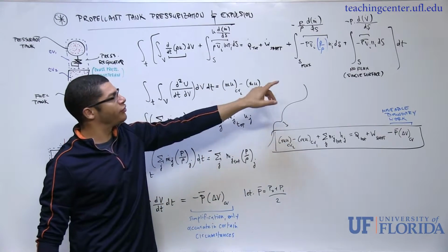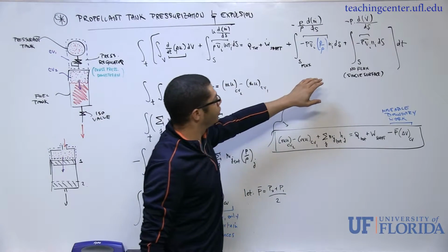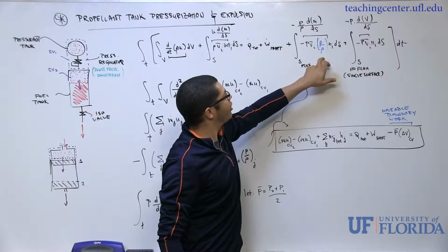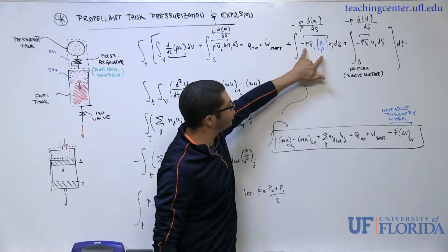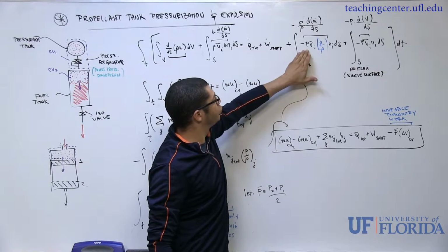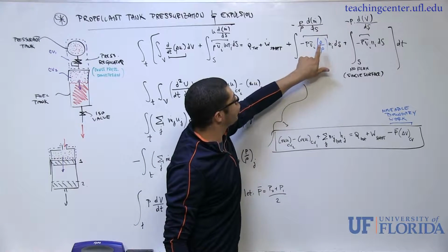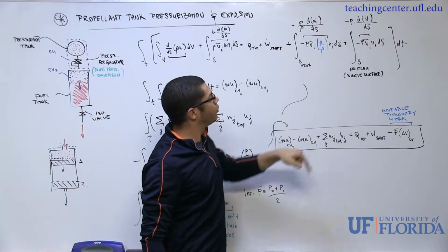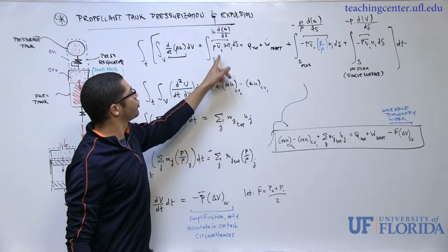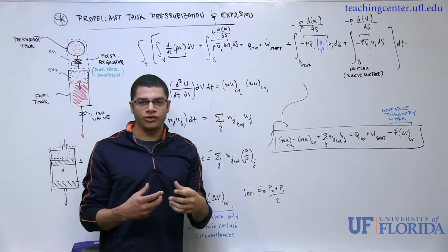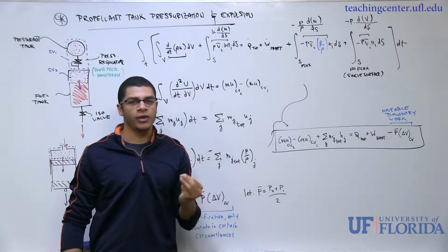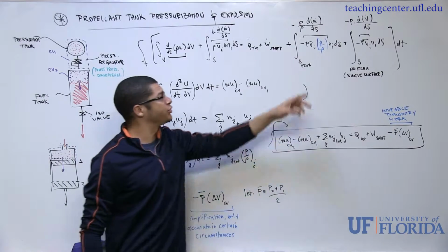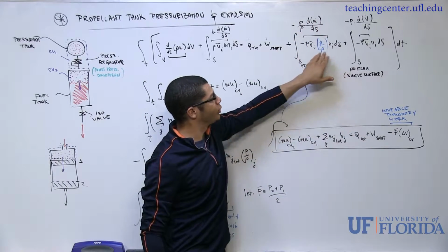And what we're doing is summing up this differential mass flux over the entire control volume surface. And a similar way of thinking can be applied over here. Because I've multiplied by rho over rho, I can rearrange this. I'll take P over rho as its own little term, and then I've got rho V. Now, rho V, like I talked about over here, is really just a mass flux, and inside this integral, I can think of it as a differential amount of mass flow rate per unit area, so dm dot ds, okay?